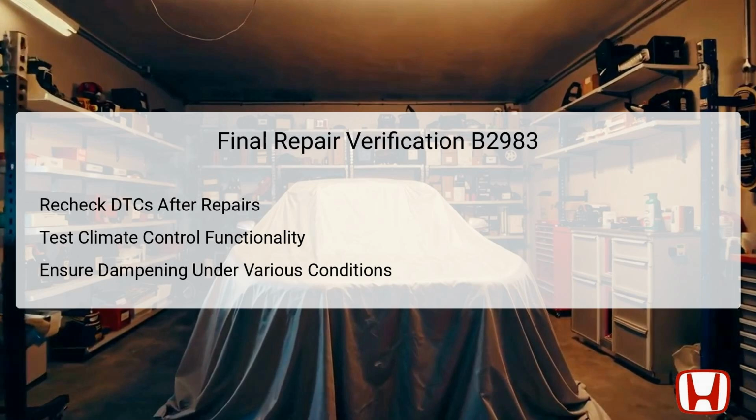Begin by clearing any DTCs once more and observing if they reappear upon restart. Following this, test the climate control functionality thoroughly across various settings, ensuring it operates as expected under both low and high demand. Monitor the air circulation, temperature adjustments, and general system responses to ensure no further issues persist. This step is essential in confirming that not just the specific fault code, but the underlying issues affecting the climate system have been addressed effectively, reinstating normal operations within the Honda CR-V.